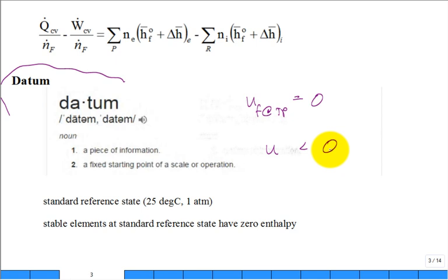How could you do that? Then the datum is set higher. So this is about 0 degrees C, I know it's 0.01 degrees C. Make it go colder, well, if you let it go colder, it turns into solid. It's ice. And ice often has a negative U, which is like, hey, how can that be? It's just your datum point.